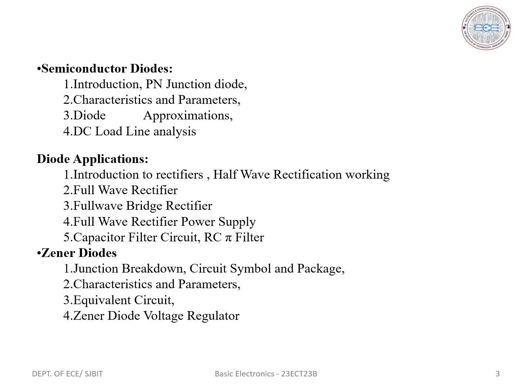Due to the presence of immobile positive and negative ions on opposite sides of the junction, an electric field is created across the junction. This electric field is known as the barrier potential or junction potential, also called the cut-in voltage, and it has fixed polarities. The barrier potential or cut-in voltage for silicon is 0.6 volts, whereas its value for germanium is 0.2 volts.